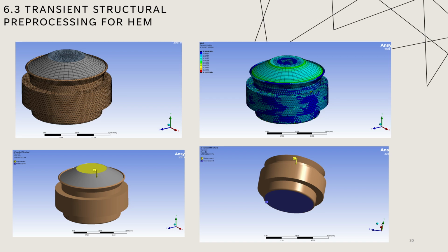And this is how I meshed my structure. As you can see on the top right corner, it's not a perfectly good mesh, but it's around 70 to 80% good. And I put some boundary conditions on it, like a fixed support at the bottom of the mount, the place that we connect to the chassis, and on top of the mount I put a displacement function by time on it, but I haven't started running it yet because my computer is not good enough to run.